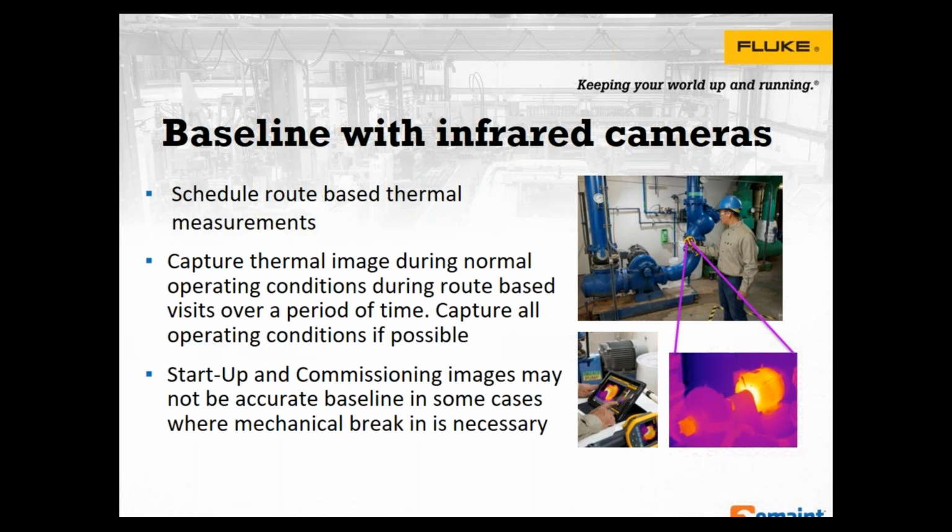It's also good to have startup and commissioning images, but I do want to say that some particular assets may require a break-in period, and when the process first starts up, it doesn't necessarily mean things are stable. The tendency is to go out there and take thermal images right after startup and commissioning, but what you really need to be thinking about is: is this normal operating conditions? Have things stabilized as far as this particular asset is concerned?